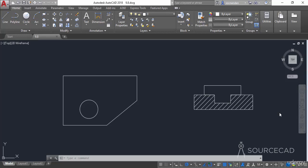In this video, I will tell you about adding feature control frames in our AutoCAD drawings. Feature control frames are added for representing tolerances and most of the geometric dimensioning and tolerancing information. So in order to add the feature control frame containing all of the GD&T symbols, you need to once again go to the Annotate tab.